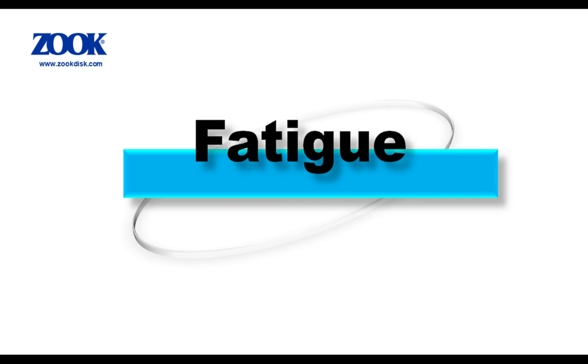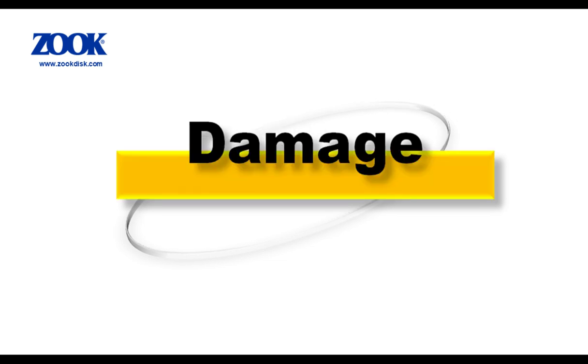Why do rupture discs fatigue? The reason is that by design there is no way to build in extra strength to allow for corrosion and loading. This is at the same time both a blessing and a curse, as the lack of over-design, what would normally be considered a safety factor, is at the heart of the rupture disc function. It is also what will give the disc a limited service life if the service conditions are demanding. This is why the disc maker should be your partner in evaluating the process and selecting the right disc from the start.